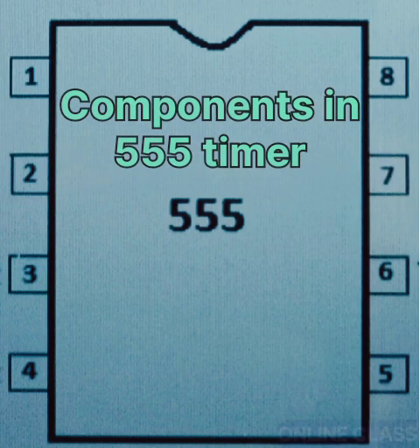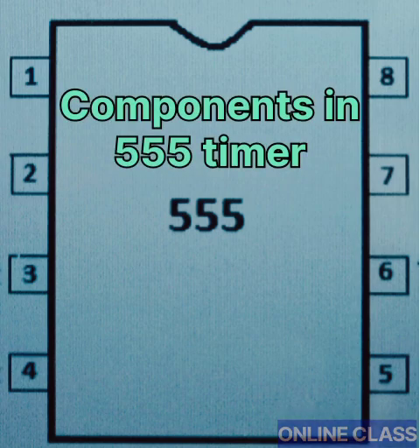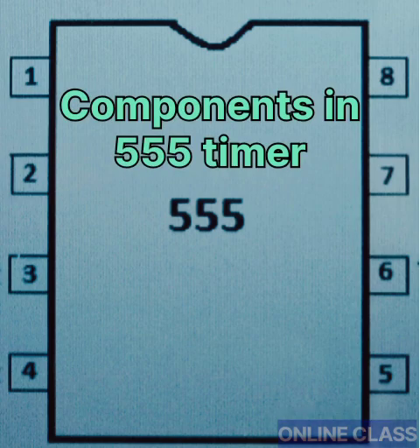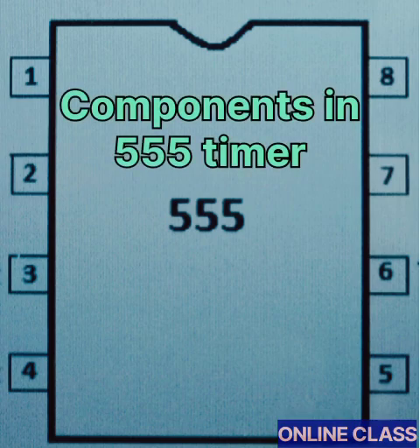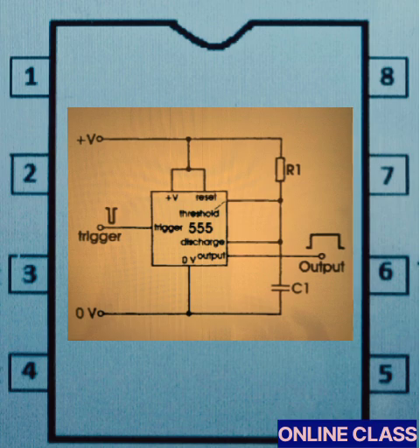The typical 555 timer package, depending on the manufacturer, contains 25 transistors, 2 diodes and 15 resistors on a silicon chip housed in an 8-pin mini dual inline package DIP8. There are variations that involve integrating multiple chips onto a single board, but the 555 timer remains the most widely used option. The diagram illustrates its use in a monostable circuit.